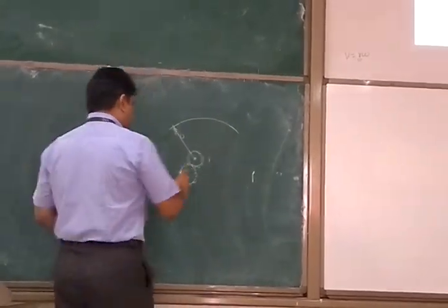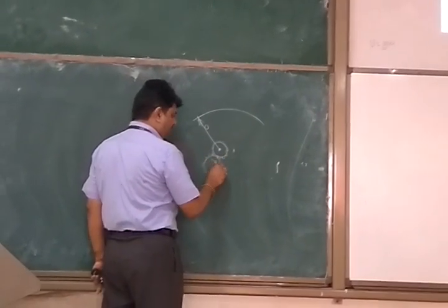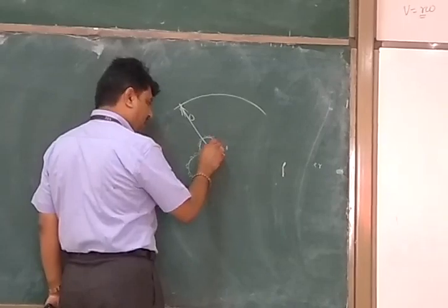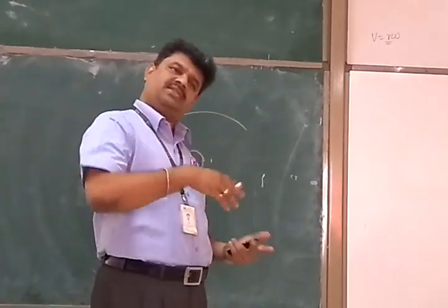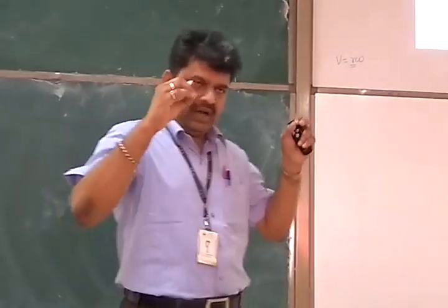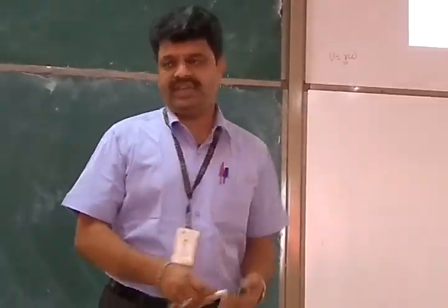So always, whenever there is a measurement, if it rotates, I want this gear to rotate, in any direction for that matter, clockwise or anti-clockwise. I don't want any motion to get lost because of backlash. That's the problem that we have.